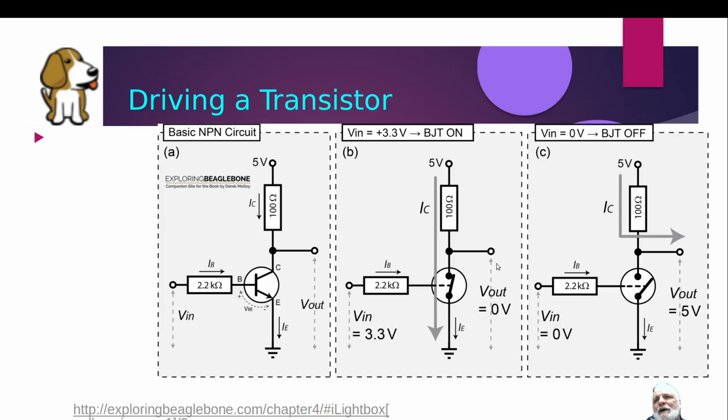When you put in a 1 here, your output over here is a 0. So this output is 0, but you will have current flowing through this 100 ohm resistor, or whatever this resistor is. On the other hand, if you put in a 0, that opens this, and so this output here would be a high. So this is what we call an inverting circuit.